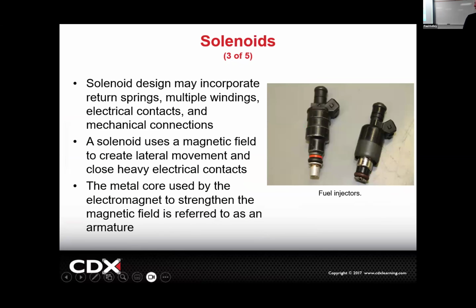And so this is just what an injector looks like solid. So the two wires come in here, one is 12 volts and one is ground, and one of them is being pulsed most likely by the PCM. And that's literally why an injector clicks. So down and dirty trick on an injector, if you start the car, you could actually put a little stethoscope on there and listen to hear tick, tick, tick, tick. If you hear the injector ticking, that means the solenoid is magnetizing and it's actually moving the little iron core.